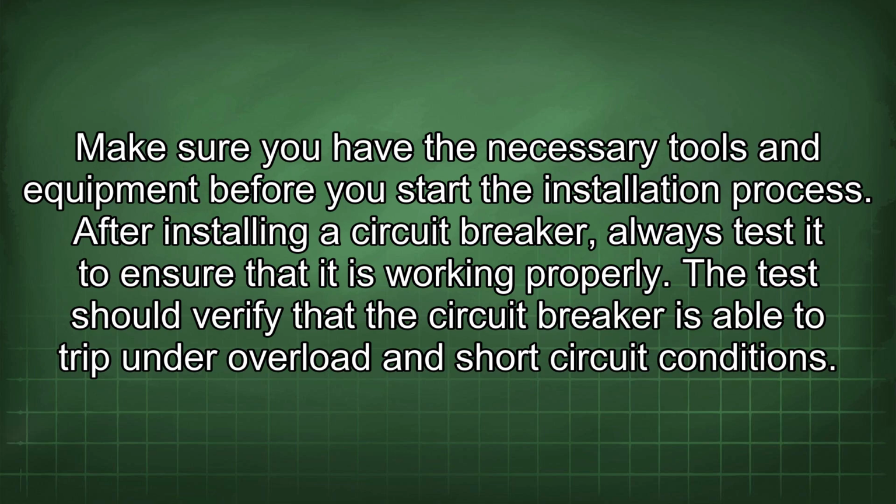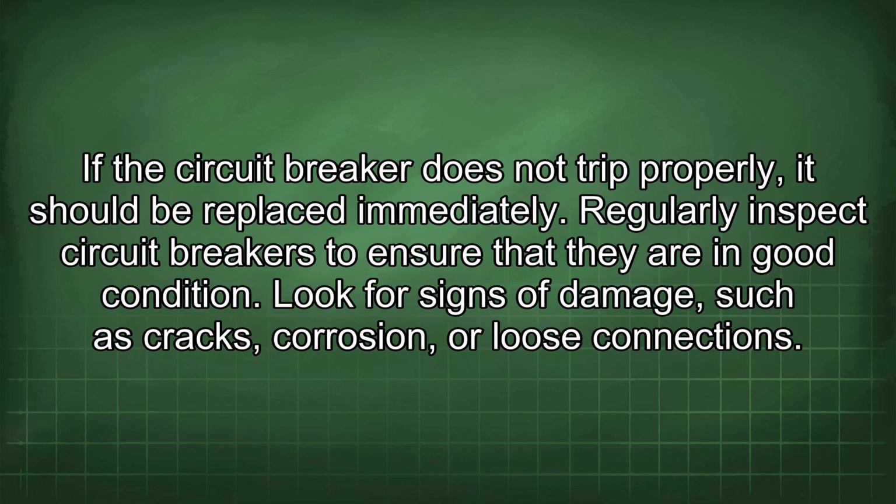Make sure you have the necessary tools and equipment before you start the installation process. After installing a circuit breaker, always test it to ensure that it is working properly. The test should verify that the circuit breaker is able to trip under overload and short circuit conditions. If the circuit breaker does not trip properly, it should be replaced immediately.